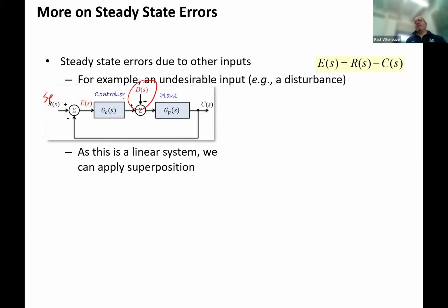You spend a lot of time and you must have looked at Jude or John and said, why do I care, why do I need to know this? Well, here's an example of being able to see where superposition is really helpful. So what is the concept of superposition? You can take any linearly independent system and find the output of such a system by taking the inputs one at a time and turning all the other ones off, then calculating what the output is going to be and adding them up at the end.